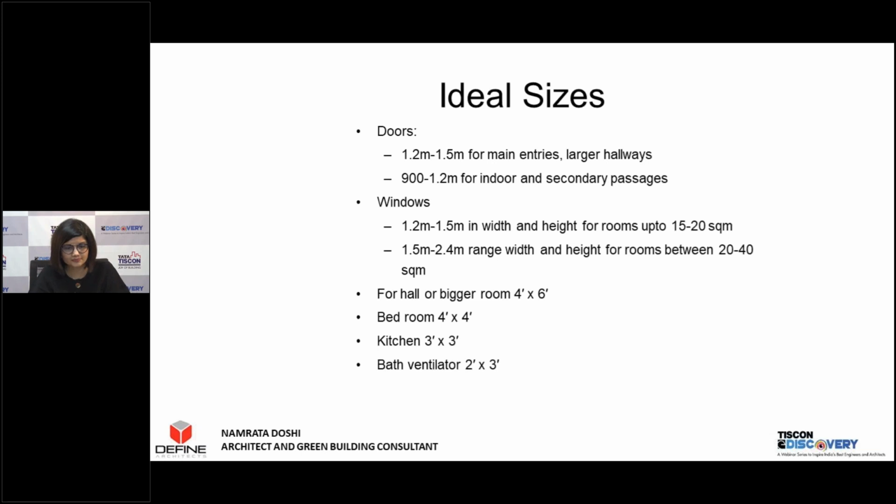Bath ventilators are typically 2 feet to 3 feet. You can give them with louvers, without louvers, and one wall usually suffices for a bath because here, the activity is for a very limited period of time. Usually, it's in the mornings for a few minutes and in the evenings for a few minutes. So, bath ventilators, you can afford to have on one wall with a smaller size.